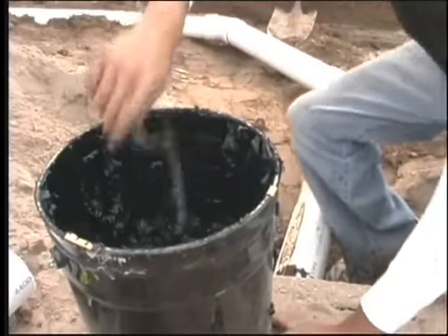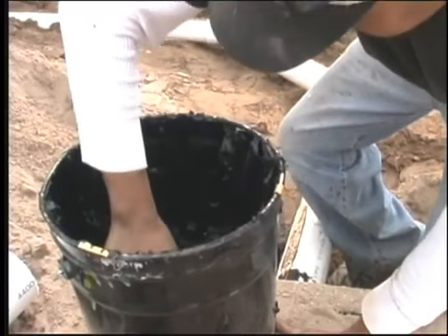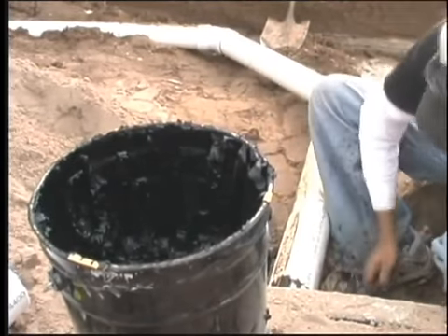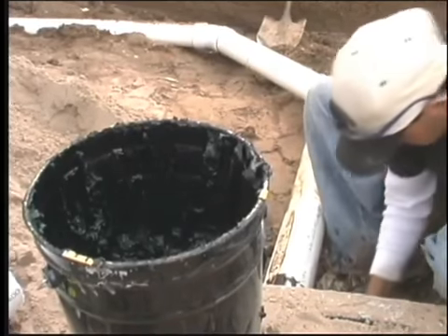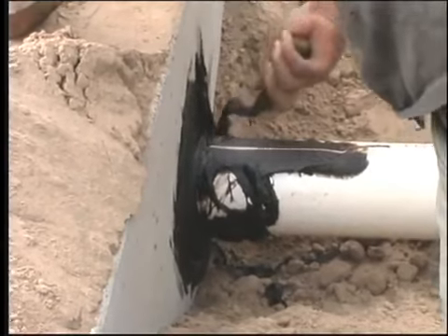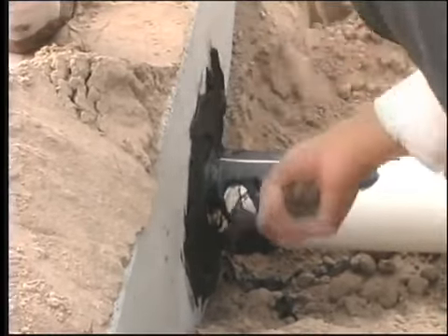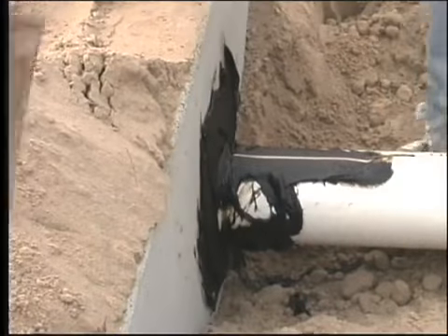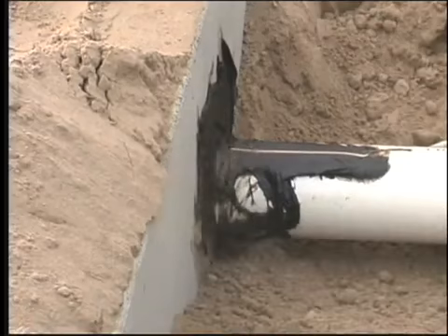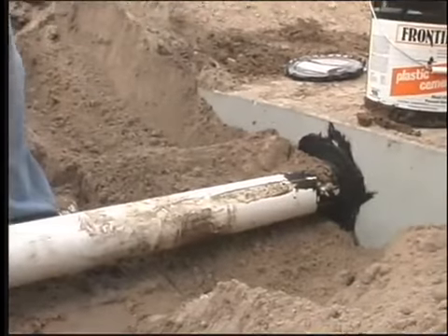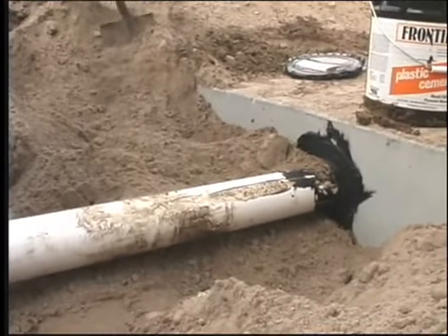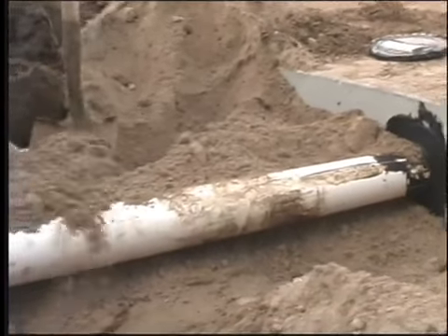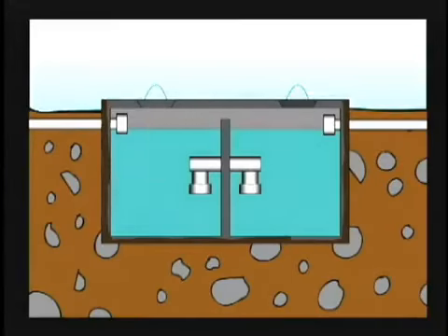When using mastic, it is important to check the pipe for adequate support. Gently press down on the pipe with your shoe. If the pipe moves, it needs better support. Without support, the pipe will settle during backfill and create a void at the top of the pipe. This may cause problems later if the tank must be hydraulically tested before it is put into service. One of the most common failure points in hydraulic testing is the top of the pipes. After the seams have been sealed, your tank is ready to be inspected and, if required, hydraulically tested.